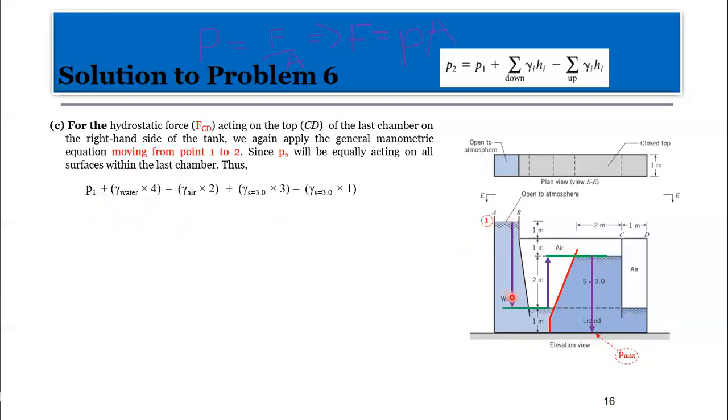We came down here, move up 2, minus, move down 3, and then we are here, right? So that is what this arrow here accounts for, the last term now. Gamma times 1, of that same fluid, right? So now, what do we need to do? This value is no more equal to the maximum pressure, but it's equal to P2, okay? And where is that 2 that we are talking about? This is the 2 we are talking about here. Okay, P2. Are we good?